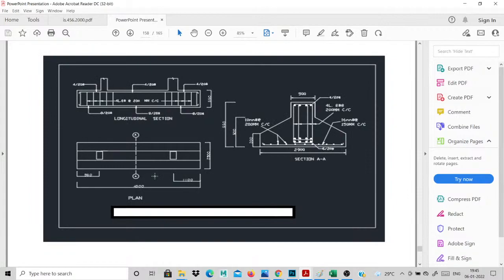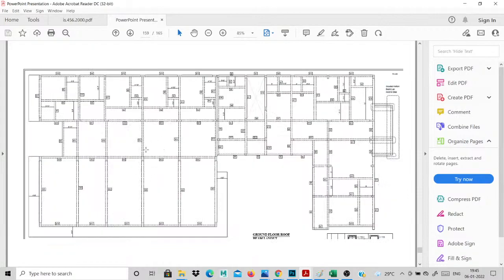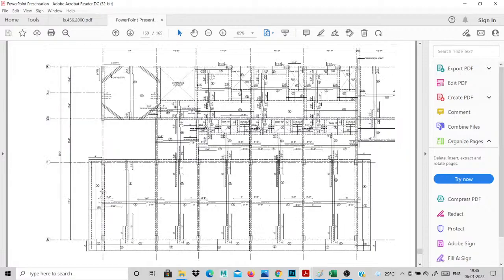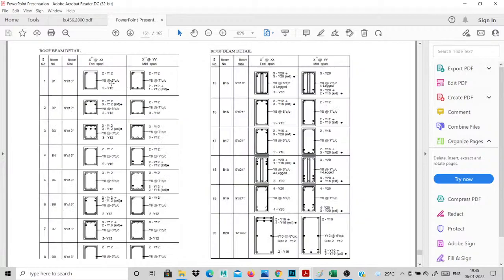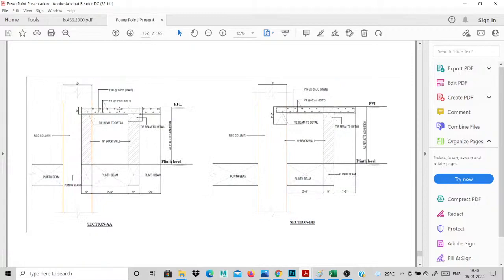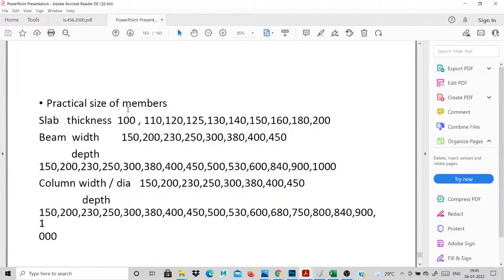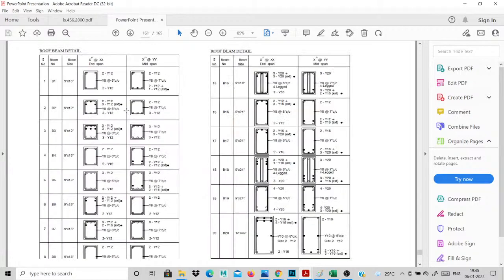Okay, this is one type of layout. You prepare another type also. See this, this is our ground floor roof beam. Mention the beam and name. This is our slab reinforcement. See this longer span one-way slab and a two-way slab also. Automatically it will be mentioned. For the two-way slab, the load will be transferred in two directions and the reinforcement will be calculated. This is the beam reinforcement for this building. Then the slab reinforcement. You provide the slab design and all the designs also.